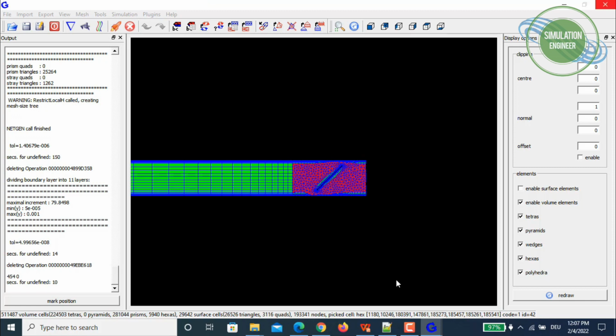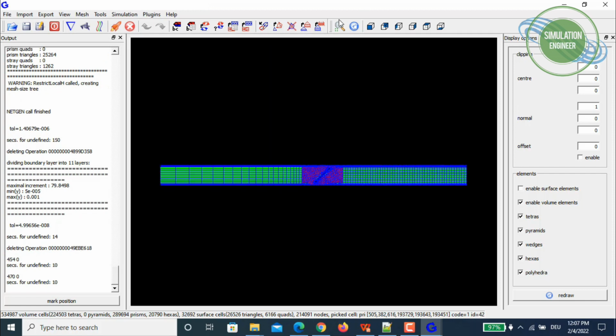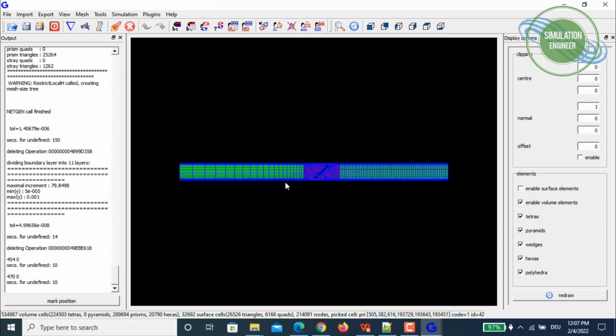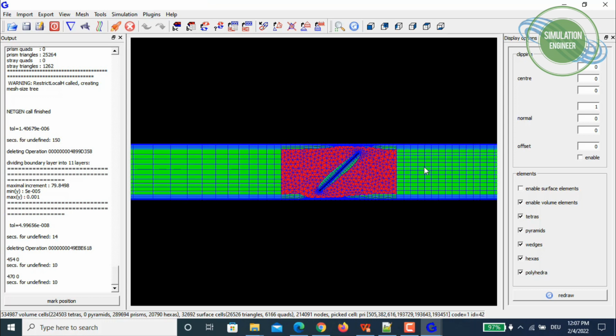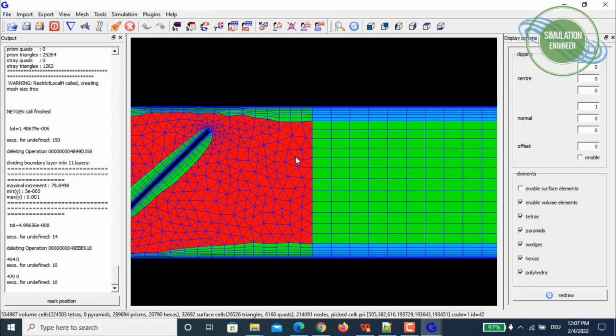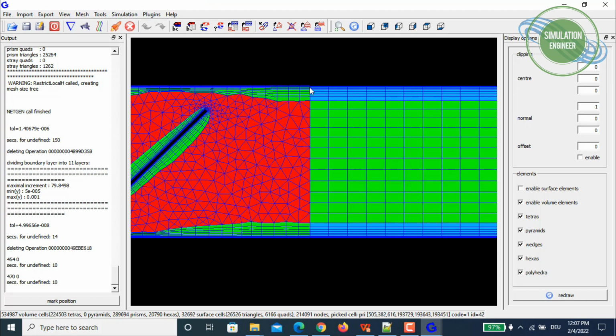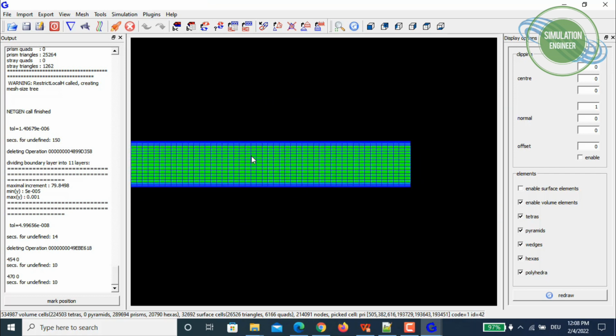And we'll see in a few moments that, similarly, now if you fit your screen, you can see we have the patches extruded, and similarly as we have seen upstream of the damper, downstream of the damper the meshes are really conformal, and even on this extension part, this interface where we extruded our mesh is working very fine.